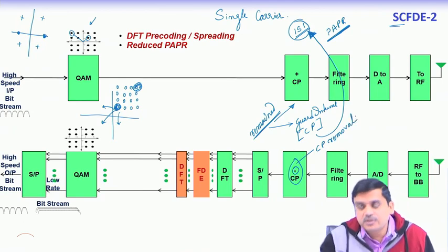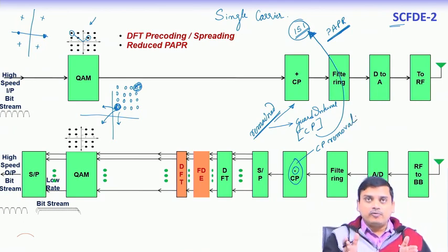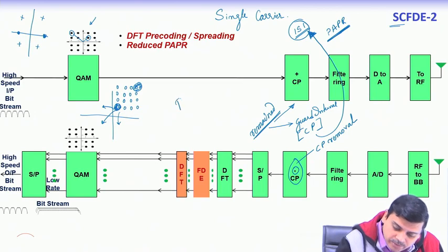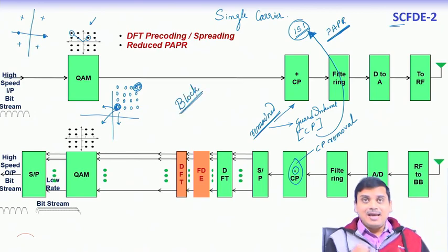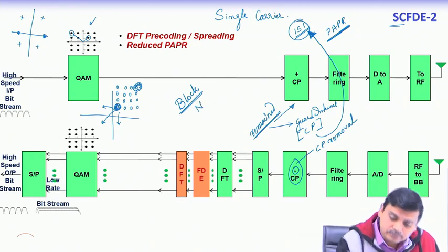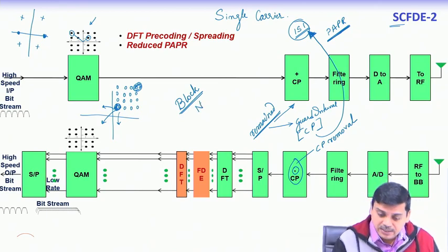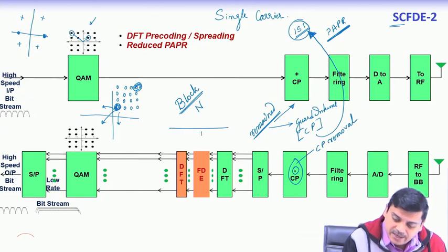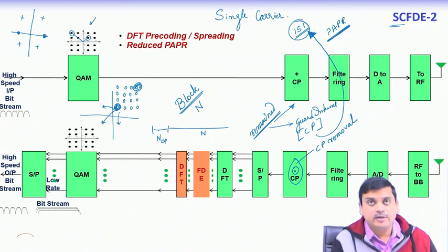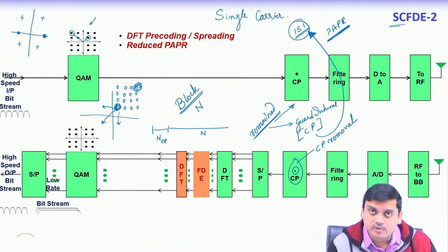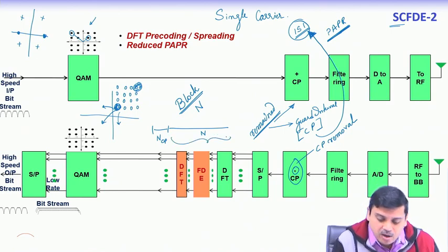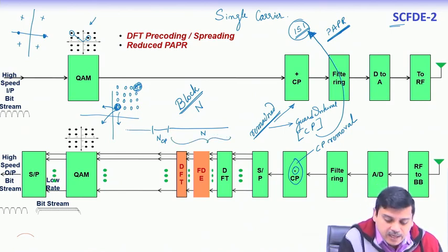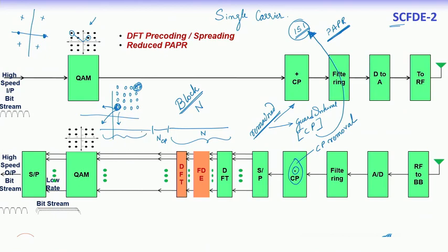So, once it removes the CP, the entire block of OFDM symbols, so we have a block based transmission, right, and the block length remains n as in OFDM, nothing has changed. So, basically that same n block length will remain and there will be a CP added to it, right. So, that gets removed and then you have the entire block which is free from the ISI of the previous block.